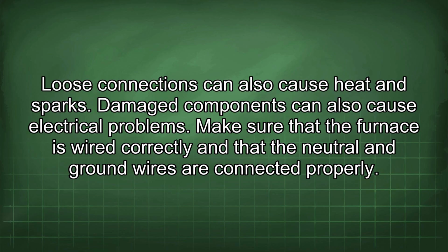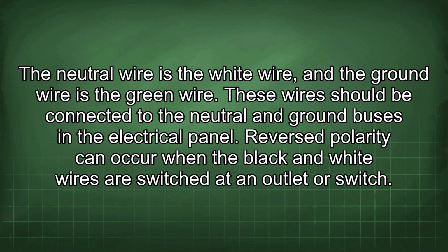Make sure that the furnace is wired correctly and that the neutral and ground wires are connected properly. The neutral wire is the white wire, and the ground wire is the green wire. These wires should be connected to the neutral and ground buses in the electrical panel.